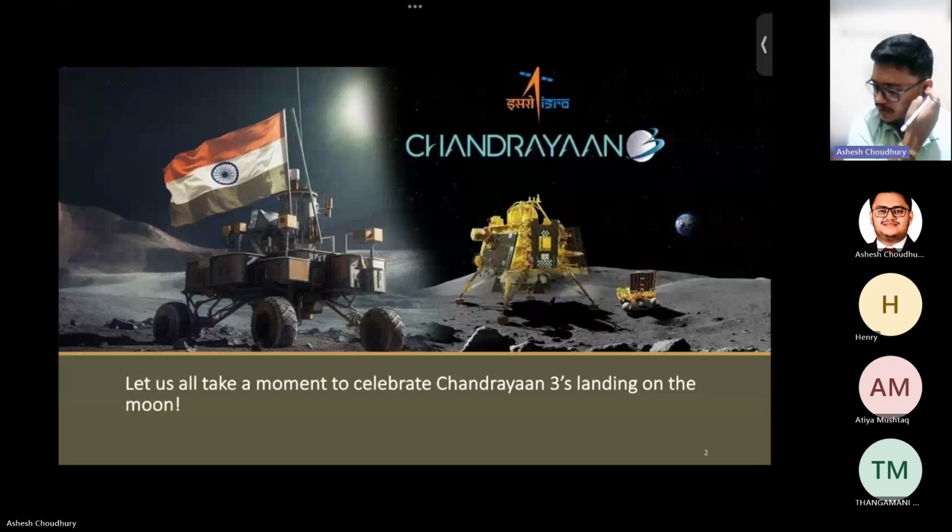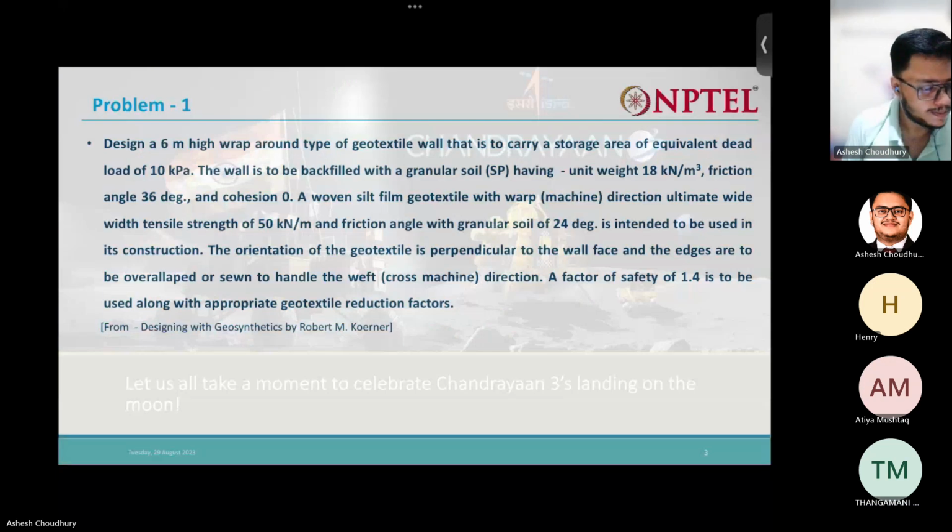Let us see the first question. Design a 6-meter high wraparound type geotextile wall that is to carry a storage area of equivalent dead load of 10 kPa.